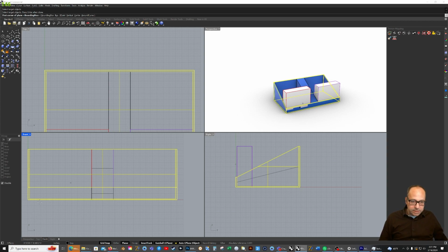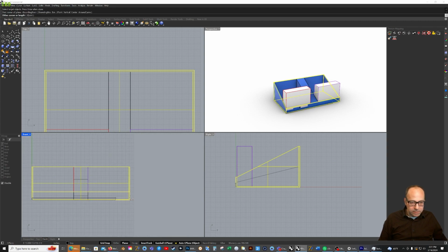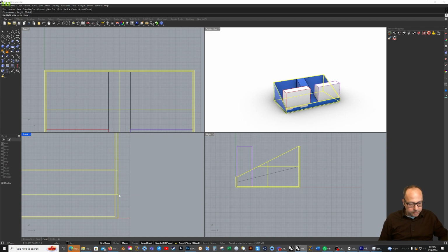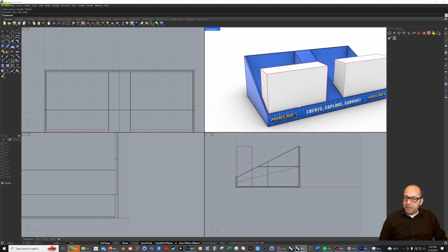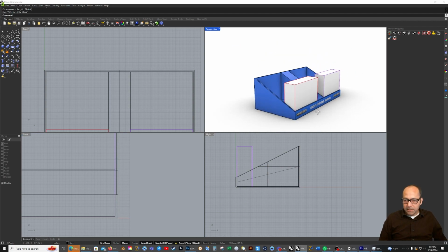Now the issue is because this tray goes 8 1/4 or 1/8 inch high, we can't just do bounding box for the lip because that's going to be too big. It's going to fill the whole area of the tray. So in this case, we want to tell it what box we want. So I'm going to click this corner and this corner, hit enter. Now you have to look up here, mapping channel 1, which is good because it's the first map we're applying. The blue flood coat doesn't count because we're not mapping that, we're just flooding it. So that put it in the right place, right size, all that.